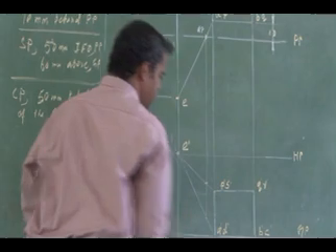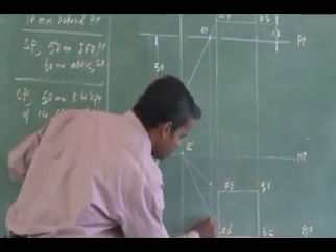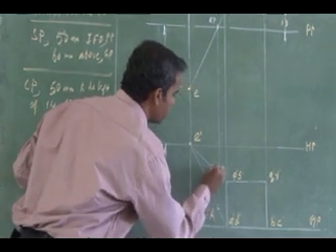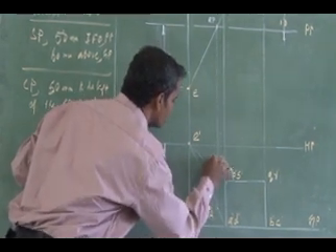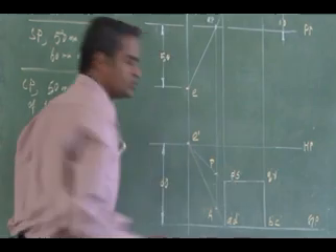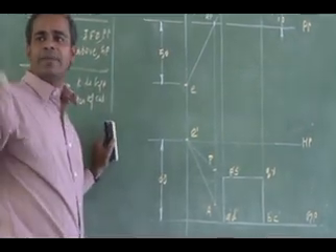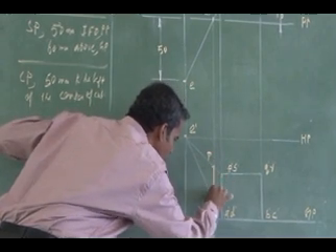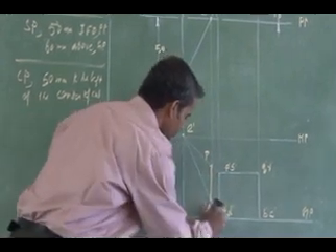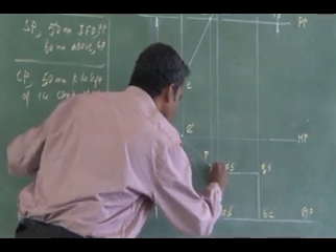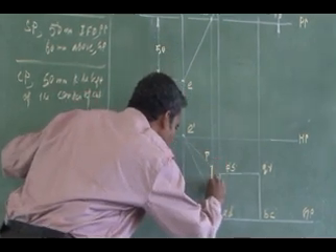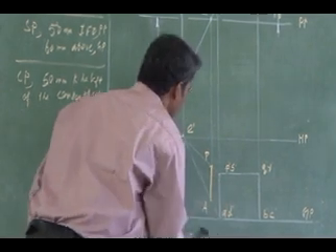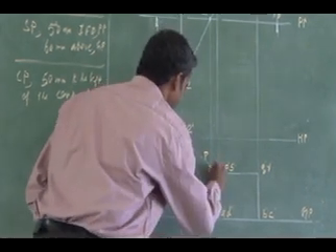So I have projected neatly. I have the perspective location of A, and I have the perspective location of P. You have to notate your perspectives in the perspective view in capital letters, similar to the isometric view. So this is the perspective view of the single edge alone, edge AB. Any clarification in this?